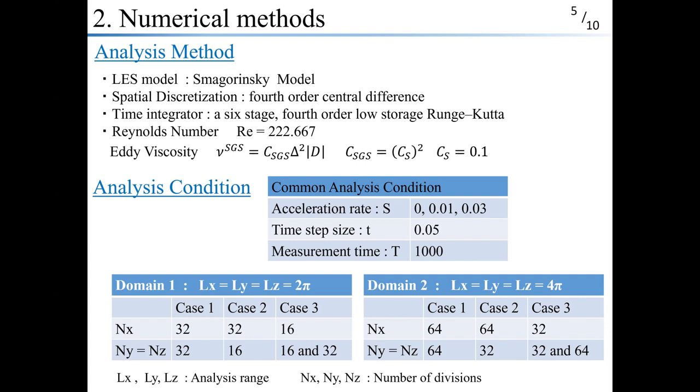The filter width defines the eddy viscosity. Simulation ran until non-dimensional time 1000. Acceleration applied from time 100 and the time step of 0.005.